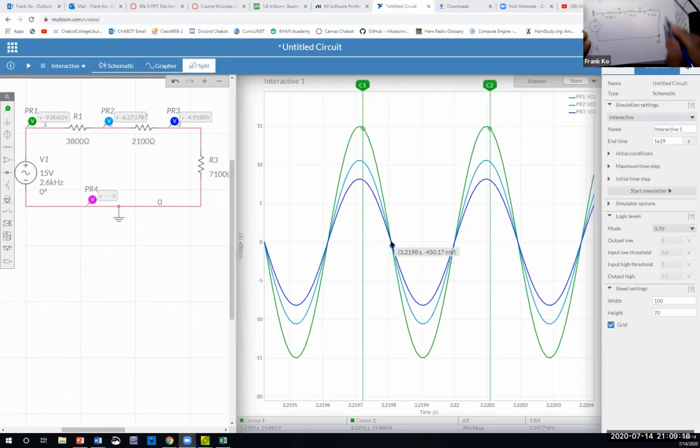Way over here. Is my ground also here? Same point, yes? So between C and ground, I have my red probe here and my black probe here. What do I expect to see between these two? Don't I see the 8.19 volts? So my voltage at point C is going to be equal to 8.19 volts. So VC equals 8.19 volts.